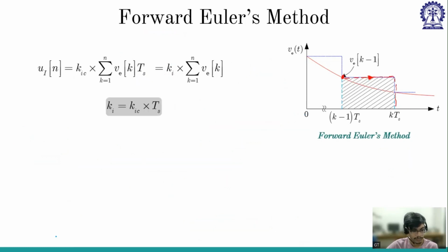Now we are taking the samples at the points which coincide with the continuous one, and considering V(t) after sample and hold. The two points coincide at one point that you are taking as the sample. If you have introduced a delay, for the time being we are neglecting delay. So this is the ideal case. If you consider delay, then also the time period will be Ts, because it will be (k-1)Ts minus delay to kTs minus delay. So effectively the difference will still be Ts.